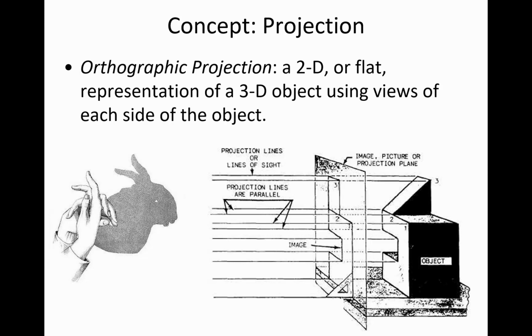And so this idea of projections is important for us because we're going to use it to determine the magnitude of the horizontal force on a curved shape. And for curved shapes, we're going to have to consider the forces in two different directions. And so this idea of projections we employ in order to determine the horizontal hydrostatic forces.